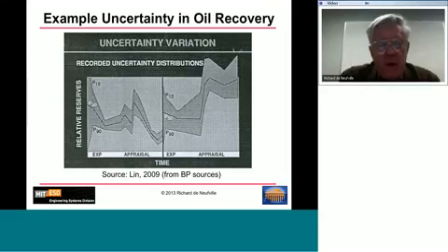And these are examples of the estimates of the quantity of oil, and these are from BP and from the North Sea. So on the example on the right, going over time from left to right, from the initial exploration to the appraisal phase, you can see that the one on the left, the P50, the most likely one, is far, far above, twice the size of what was actually determined to exist later on. And if you design for the P50, you'd have something which was much too large for the actual situation. On the other hand, with the other one, on the right-hand side, if you design for the P50, you'd be about half the size of what was actually needed later on. This is just an illustration of the kinds of things that happen. And as you can see, the uncertainty does not narrow down quickly into an average value. It jumps all around. This is very typical of actual situations.